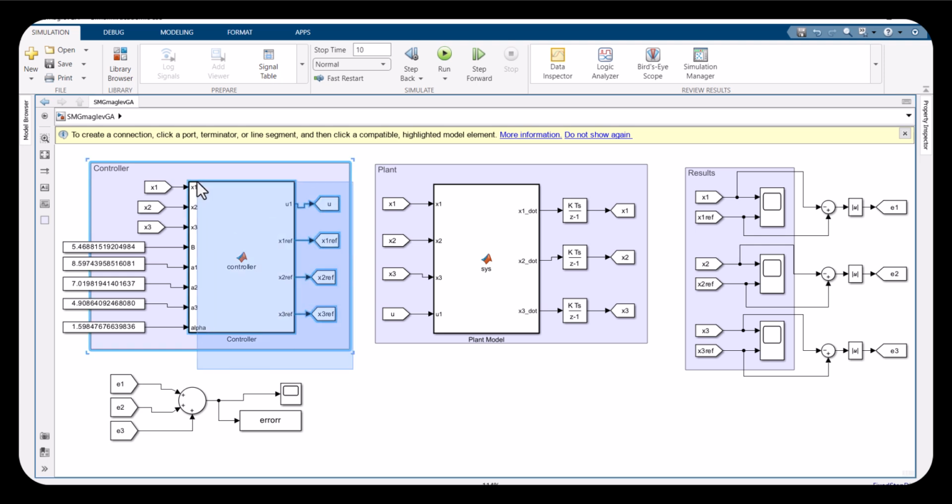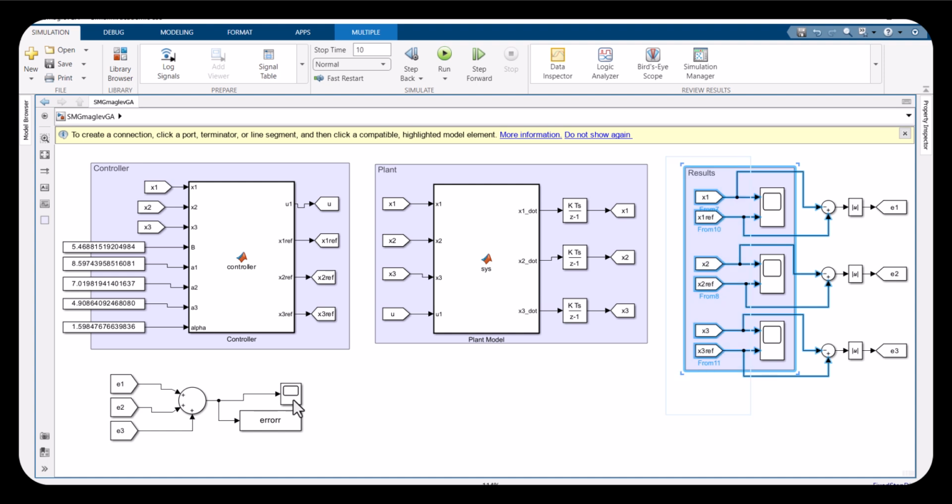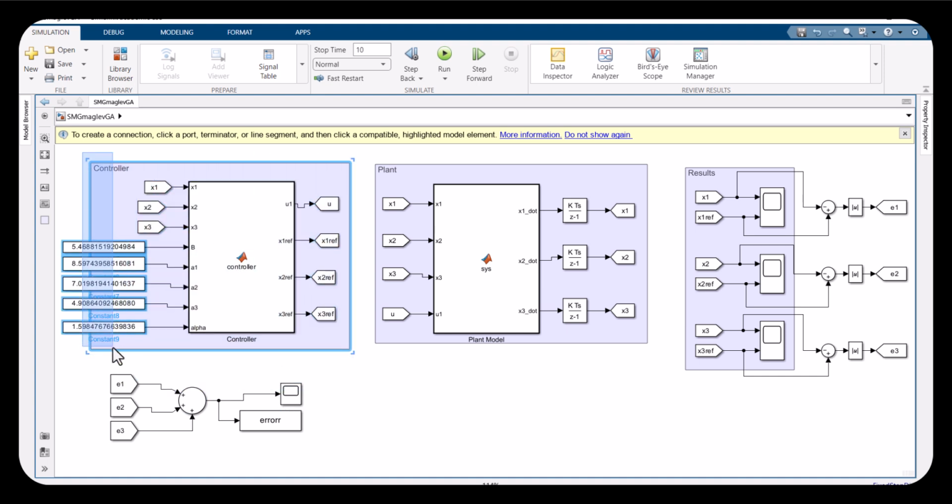This is the third part of this series. First we designed the controller for this magnetic levitation plant. We observed the results, and then we saw that different values of these gains will give you different results. So we decided to use optimization algorithms to get the best values of these gains, and we used genetic algorithms. We designed all of this to compute this final error, which was used by the genetic algorithm to get these values. So once we have this optimized control law with these optimized values, we got our final results.